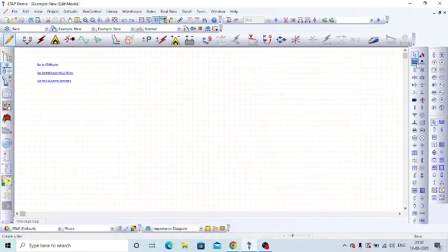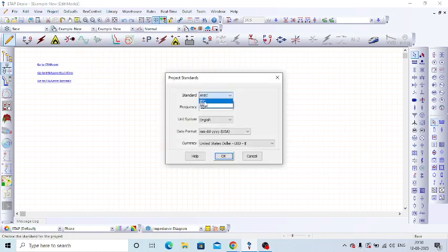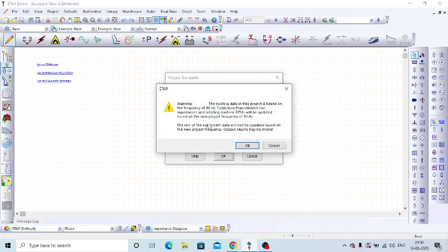Okay, good. So I will continue with the short circuit studies. First we need to build the single line diagram. It is similar to our load flow analysis. First of all, we would like to do the settings. So I will select IEC and 50 Hz frequency.